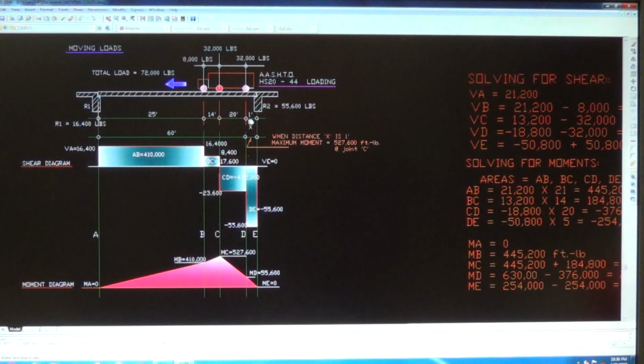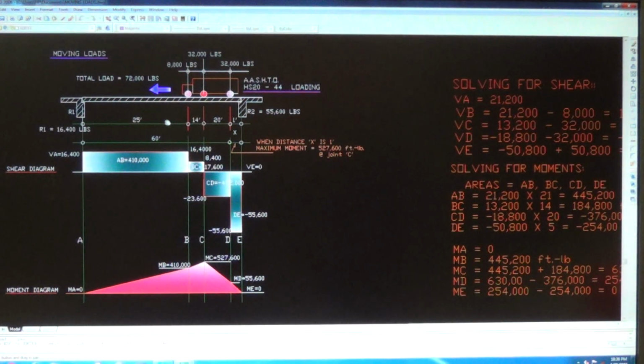When the wheel is 1 foot away, look at the shear here. The shear is 55,600, and for the second video it is 5 now. It becomes smaller and smaller up to the midspan, where it becomes like 0. The diagram for shear is going like this, going down to the midspan. This is the largest shear, and it goes inclined like that, and it goes negative all the way to the other reaction. See, this is the testing rate. See, 1 foot. You can't get any greater than this shear for sure. I know that.